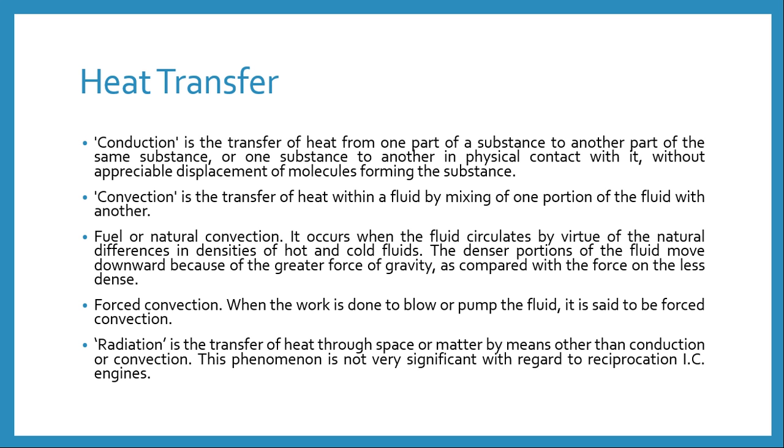The flow of fluid may be forced by external processes, or sometimes by buoyancy forces, which are caused when internal energy expands the fluid, thus influencing its own transfer. The latter process is called natural convection.